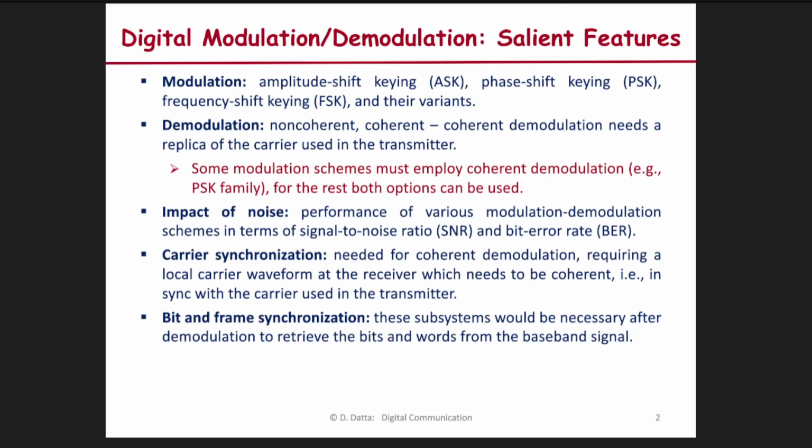So if the frequency is 10 kilohertz, then lambda becomes 3 into 10 to the power 8 meters per second by 10 to the power 4 hertz. That becomes 3 into 10 to the power 4 meters, a huge 30 kilometer antenna size. Can you imagine? Whereas if you go for 10 gigahertz, the wavelength becomes 3 centimeters, and the dipole would be half of that. So the transmitter antenna size also comes down to a very practicable, realizable value.